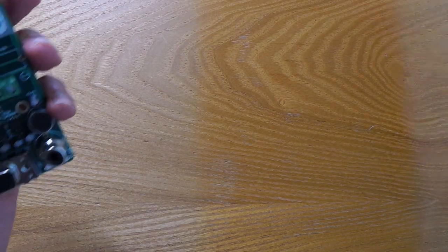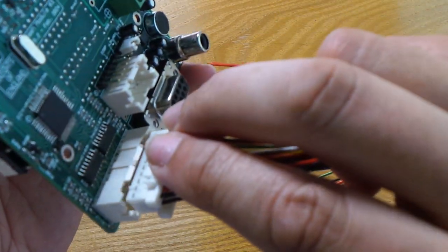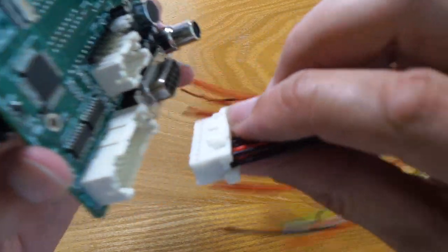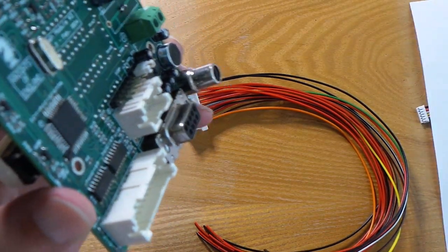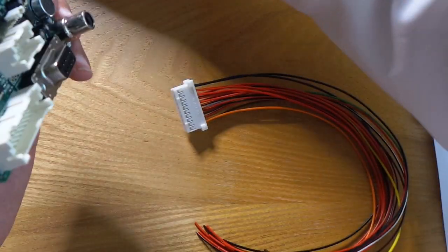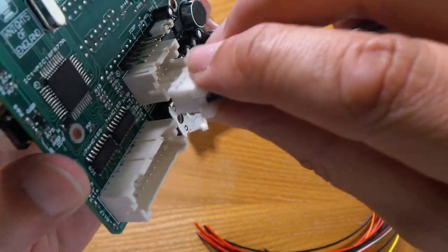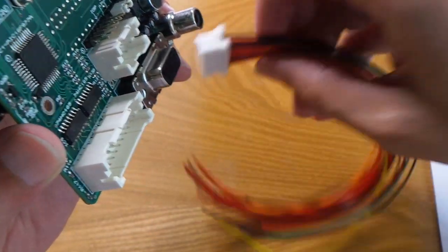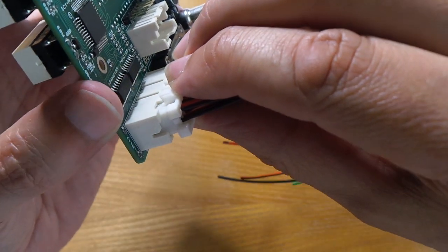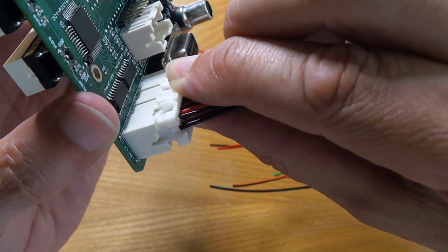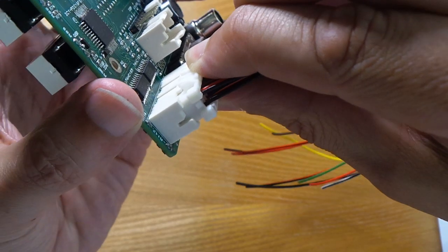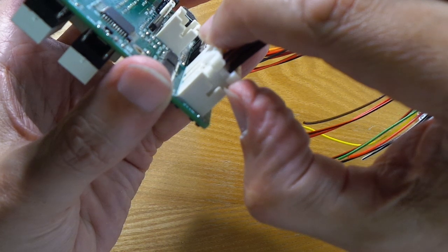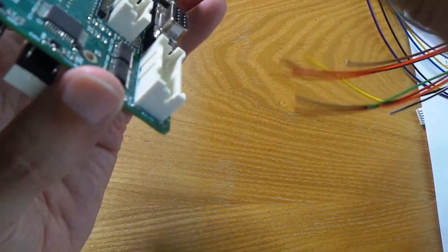I will just mention actually that when you put these JST type connectors in, they will snap into position quite easily, but if you want to remove them, this one, the 10 pin connector, isn't so bad. You can just push that tab in and pull it out, but the 20-way connector, because it has more pins, is quite tight to remove, so you'll need to pull that tab down, and then get a small flat screwdriver between the edge of the connector and the body of the connector and pry it up. So I'm not going to connect that now.